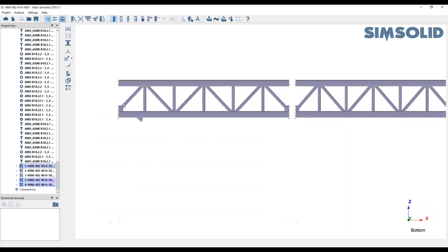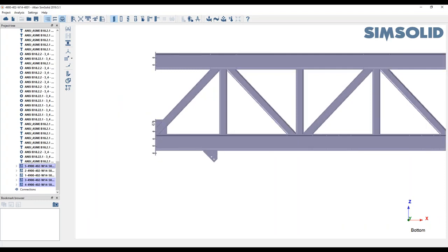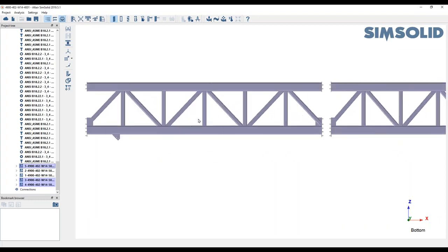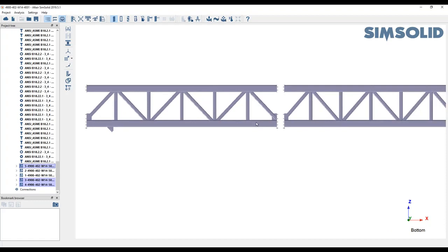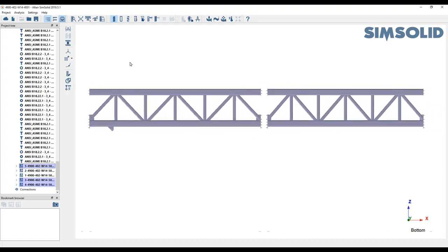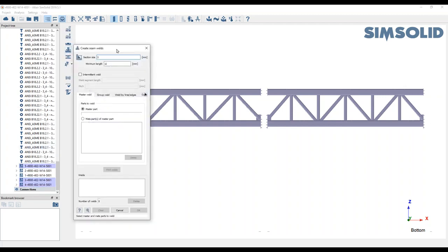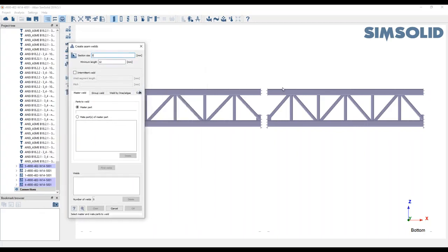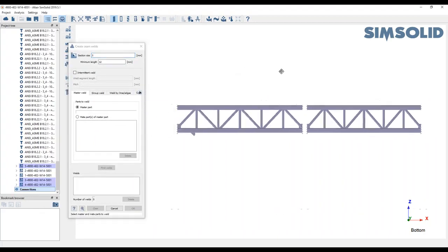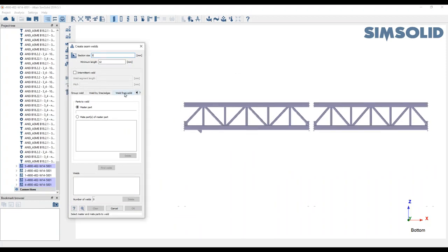So I have got the bolted connections, but it's not going to weld the bolted connections and the holes because we're going to set a tolerance for my welds for a minimum size. So let's zoom out again. Okay, in the connections, I have various options. We're going to create a seam weld, and there are numerous ways we can create the welds. Now you can see here you can create a weld from a solid geometry. So if you're using weldments, or create a fillet or a chamfer around a box section, you can take a geometry and represent that as an actual physical weld.